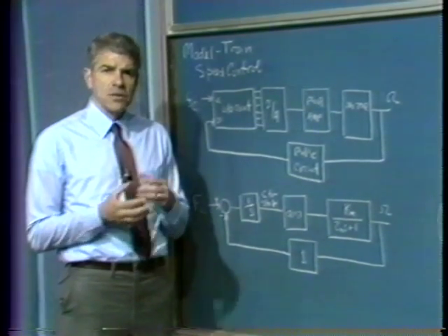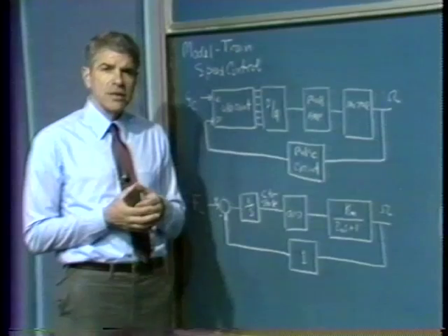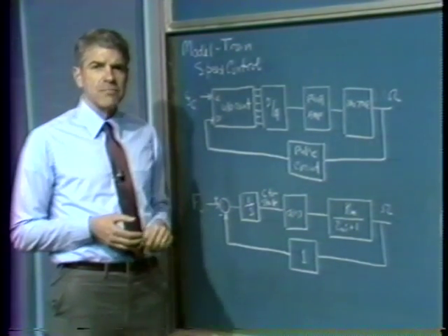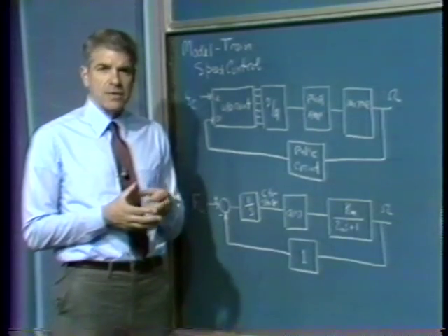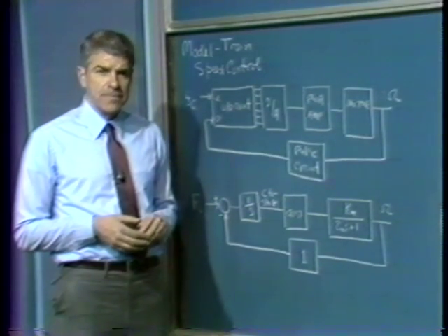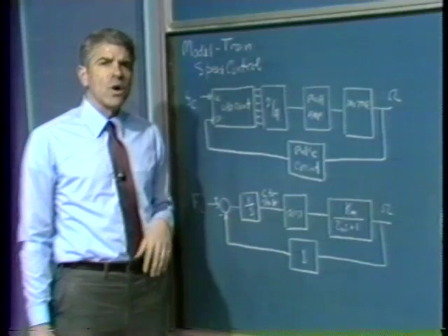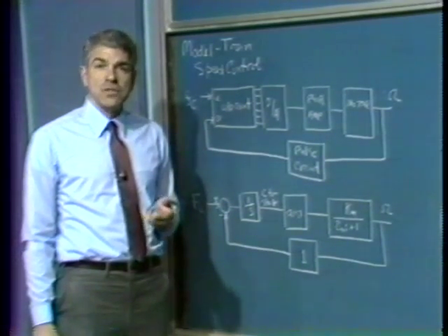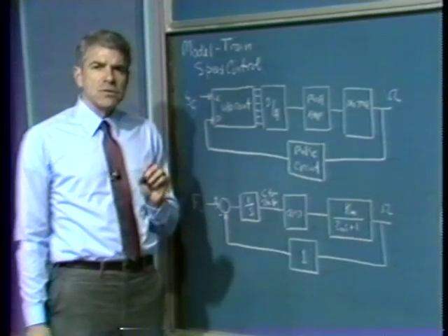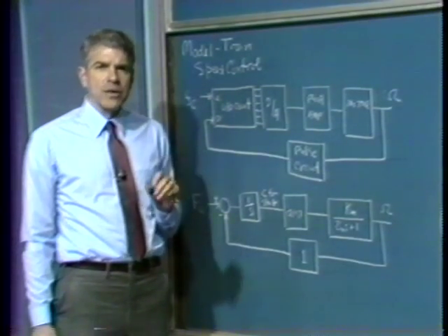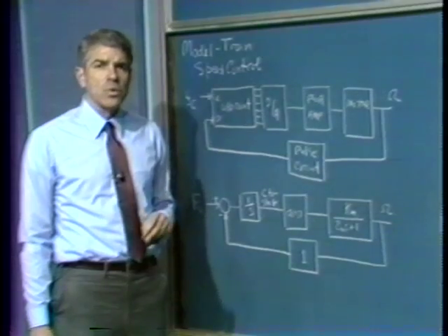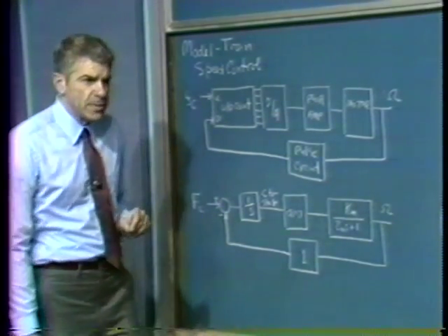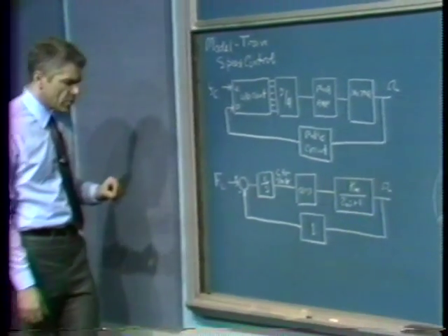And so you get 6 large spikes in operating current per revolution of the armature of the motor. That, of course, translates to some distance traveled, reflecting the gear ratio and the size of the wheels and that sort of thing. But those spikes are quite easy to detect. And so you can use that as your indication of speed. And you can use those commutator pulses, appropriately shaped by some sort of a pulse network, to really mechanize a phase lock loop. And the phase lock loop looks something as follows.